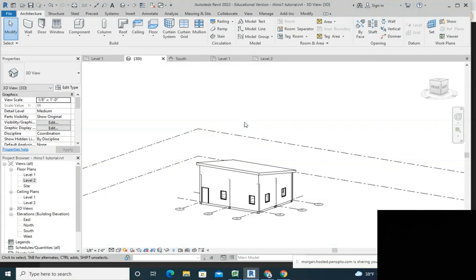Now you're making a boundary line. So click on the rectangle, and then click on the side, and then click all the roof. Cancel. I think it just clicked too soon. So click on boundary line again. Click on one corner, and then click on the other corner. To offset it, you're going to use that tool. Yep. Offset it all the way around. Okay, then delete the inside lines and hit escape to get out of that command.